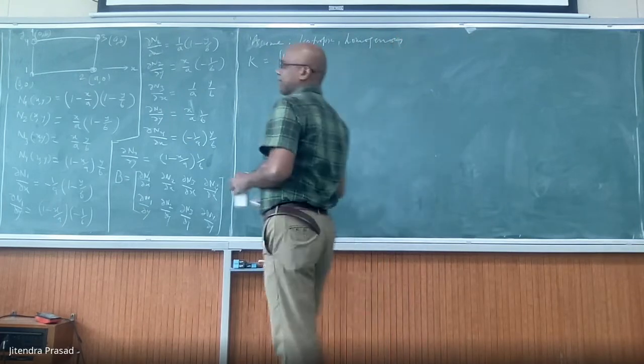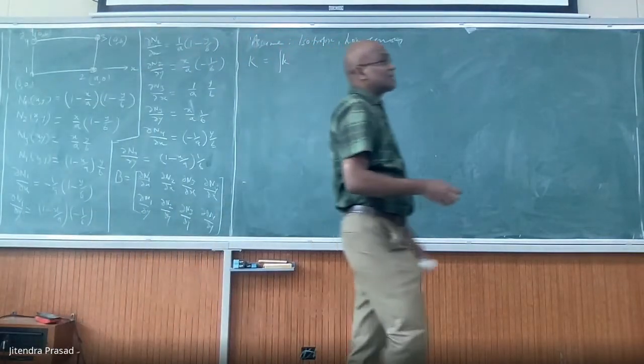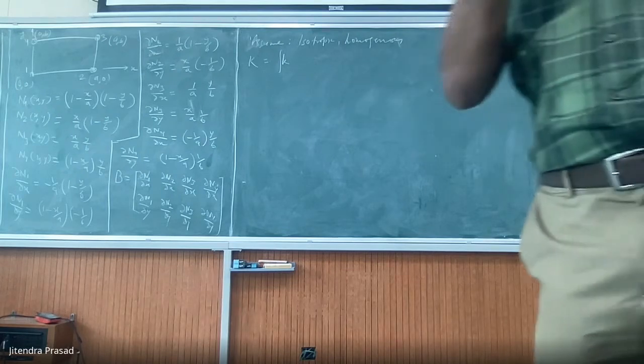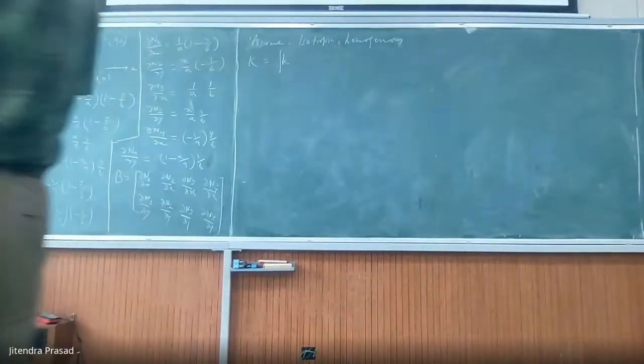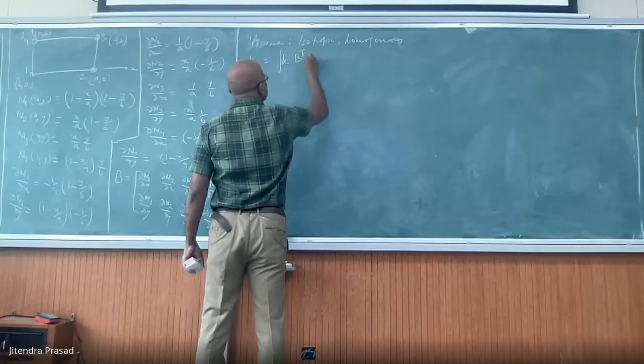So typically when you work with commercial software like Abaqus, they will ask you what kind of material you want, right? Isotropic, homogeneous material. Otherwise you say inhomogeneous, which means k is varied, and in that case you have to define the region here where k is different, the region here where k is different, and so on. When k is a function of x, y, then you have to write a subroutine, typically in Fortran or Python and so on.